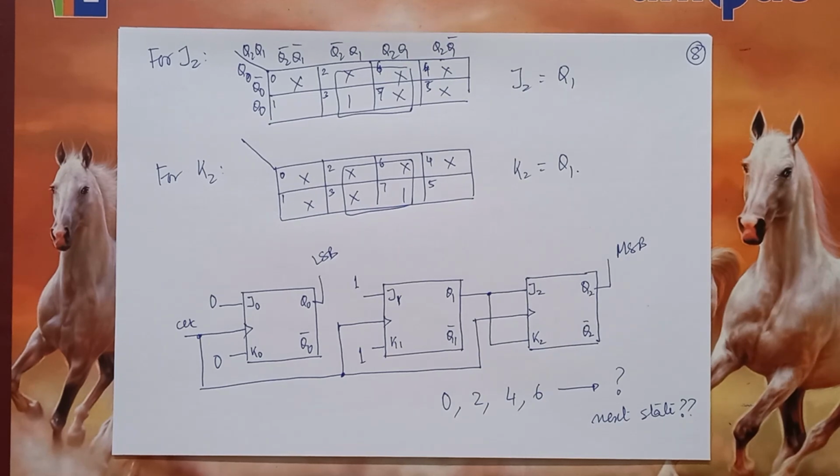And we also saw two techniques. One, where the undesired states are being forced to 0 or some known state as a next state, which is very, very demanding in terms of additional logic needed. And the second technique is where the undesired states were left as don't cares for the next state, which reduced our additional gate requirement considerably. But the danger over there is that you will need to ensure that those unwanted states come back to the desired counting chain at some point or the other.